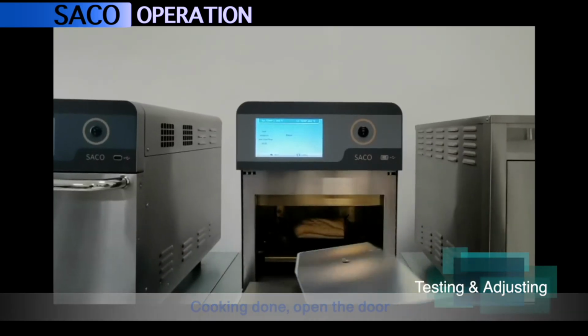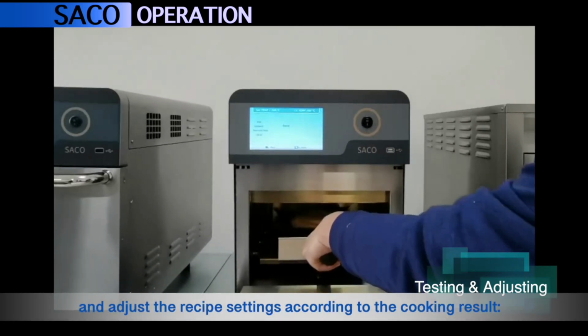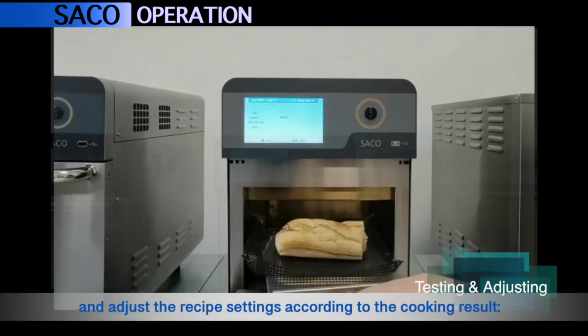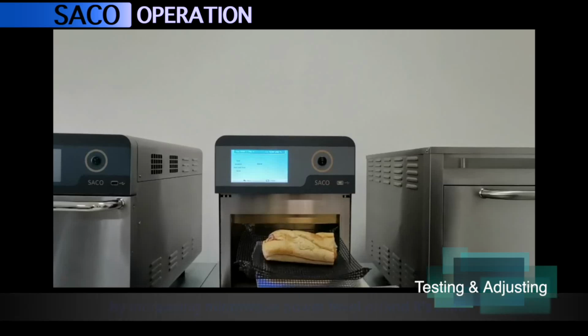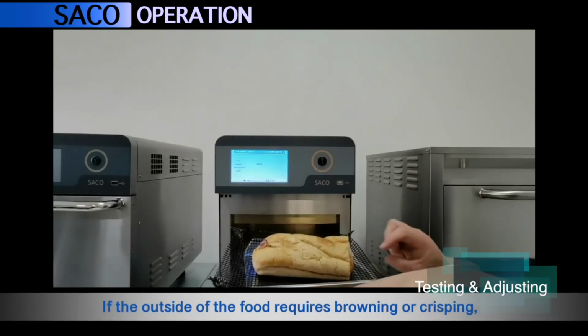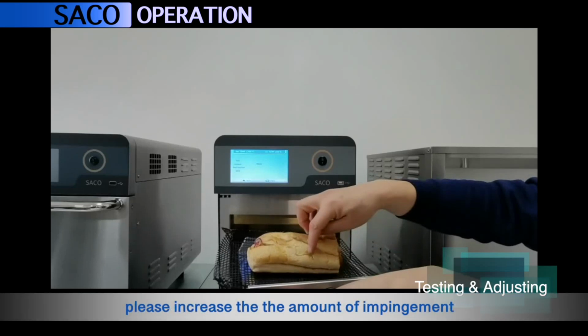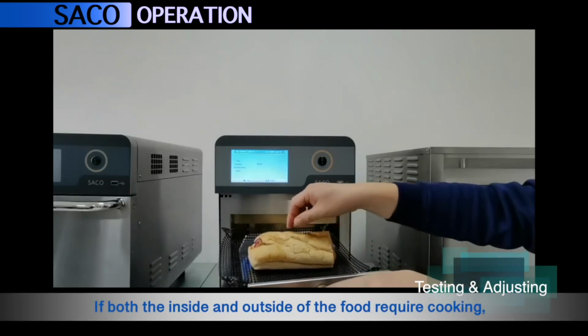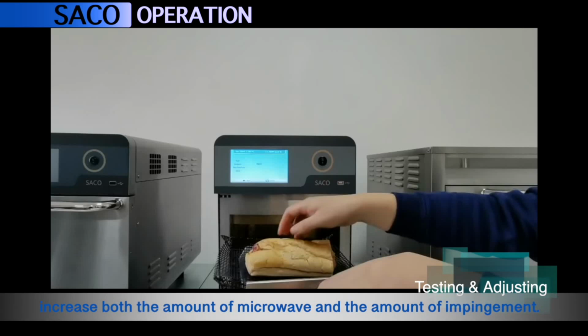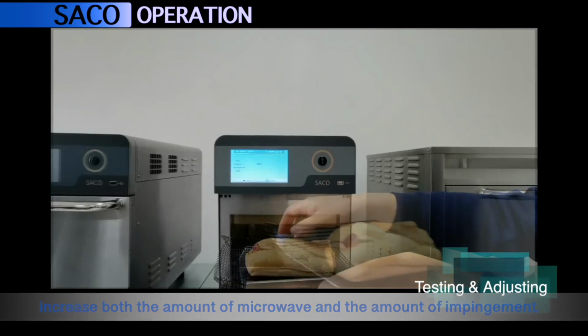Cooking done, open the door, take out the sandwich to check it, and adjust the recipe settings according to the cooking result. If the inside of the food requires cooking, for example, the inside temperature is low, please increase the amount of microwave by increasing the microwave power level and its time. If the outside of the food requires browning or crisping, please increase the amount of impingement by increasing the impingement levels and its time. If both the inside and outside of the food require cooking, increase both the amount of microwave and the amount of impingement.